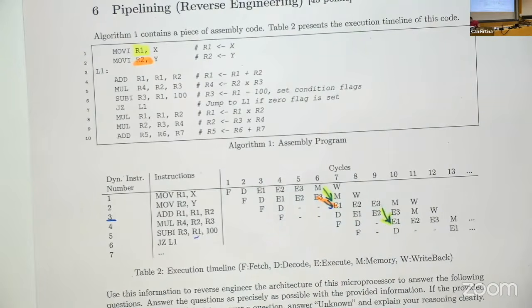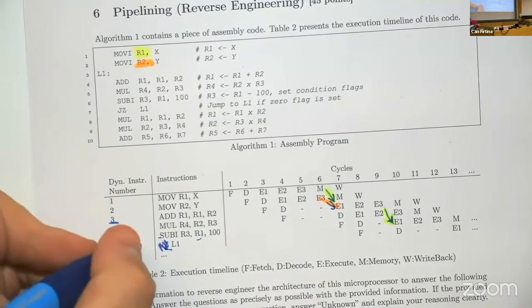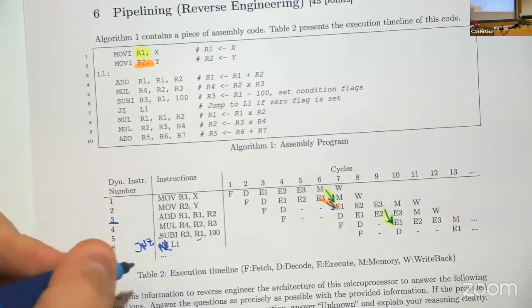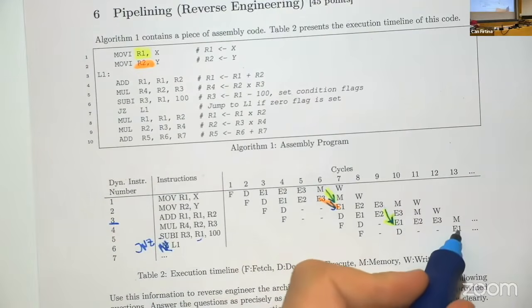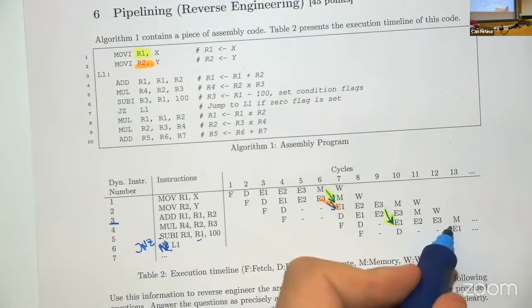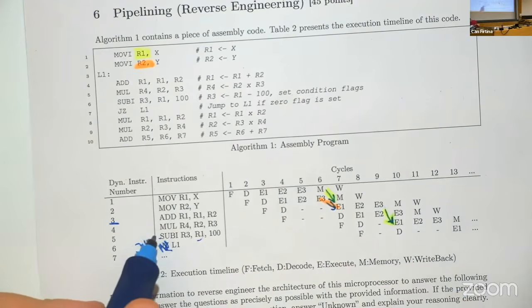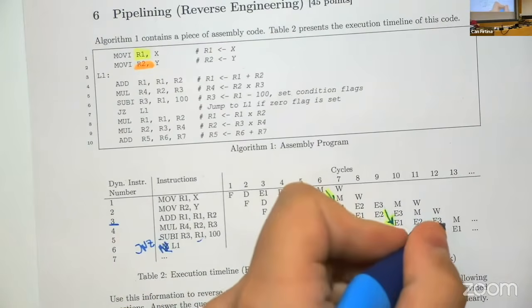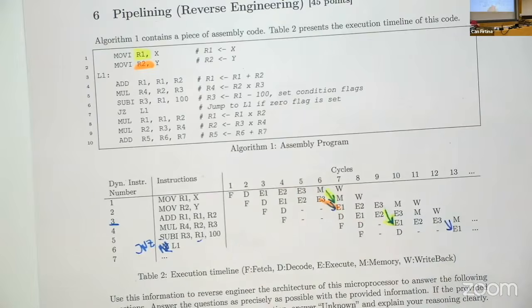And the second thing we're seeing in the remaining stall is the jump condition. The question says jump 0, but it should actually be jump not 0. I guess there's still an issue in the question here. This jump condition is checked here in E1, and it awaits the value from this subtraction. So it jumps if this subtraction is not 0. So we also have some kind of forwarding path there from E3 to E1.